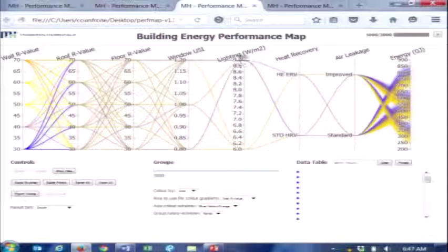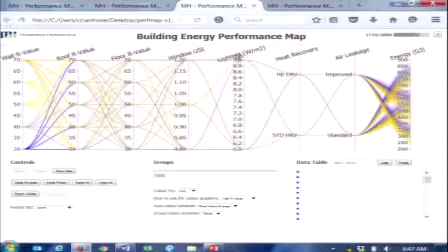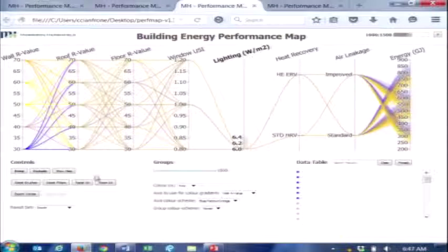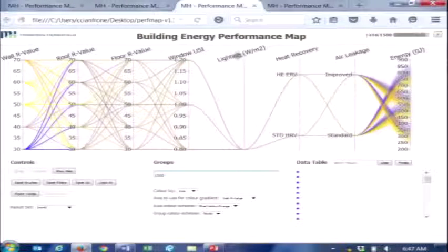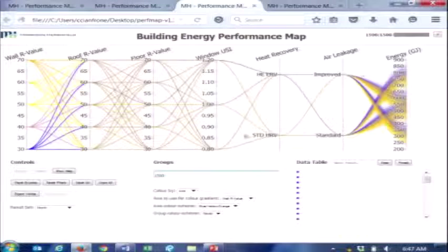And then we also looked at LED lighting. And this became sort of one of those things where LED lighting proved to be cost effective, but it made just a drop in the bucket in terms of overall energy efficiency because it was a heating dominated building. So it was an analysis that you could have done on the side. It didn't necessarily need to be integrated with the heating measures, so we can remove that from the picture.